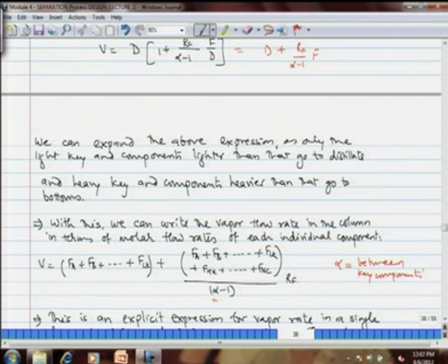So, when you apply this particular expression for each column, you have to see carefully as where the column is splitting the feed. So, if the column is separating A, let us say you have a 5 component mixture and the first column separates A from B, C, D, E. So, the split is between A and B, because components heavier than B are all going to end up in the bottom. So, for this alpha you have to use alpha AB, but in the next column let us say BC is being split from DE, as in one of the sequences we saw. Okay. After separation of A from BCDE, we are left with quaternary mixture BCDE, and let us say that quaternary mixture is being split as BC and DE, then you have to use alpha CD, because there the split is between the key elements C and D.